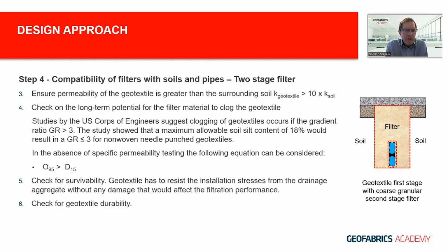Next check is check for survivability. So we have to ensure that the geotextile remains intact when it's installed and the granular material is placed and compacted on top of that geotextile. And then we also have to look at durability. In the case of geotextiles, durability is not normally an issue. Most soils are pretty benign, and geotextiles are not a nutrient for any biological attack.